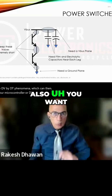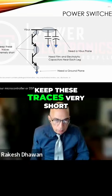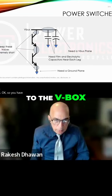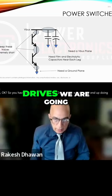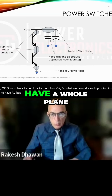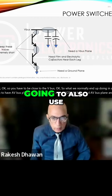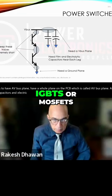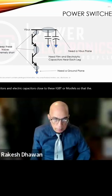Also, you want to make sure that you keep these traces very short, okay? So you have to be close to the V bus. What we normally end up doing in low voltage drives is we have a V bus plane, a whole plane on the PCB, which is called a V bus plane. And then we also use film capacitors and electrolytic capacitors close to these IGBTs or MOSFETs so that the impedance between this point and this point is small, right?